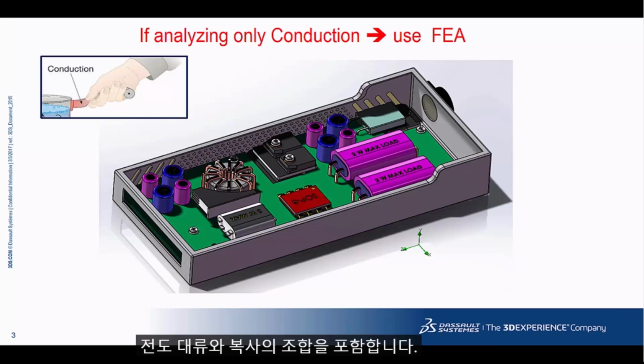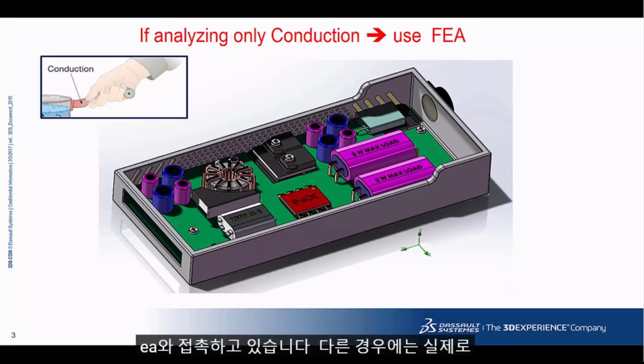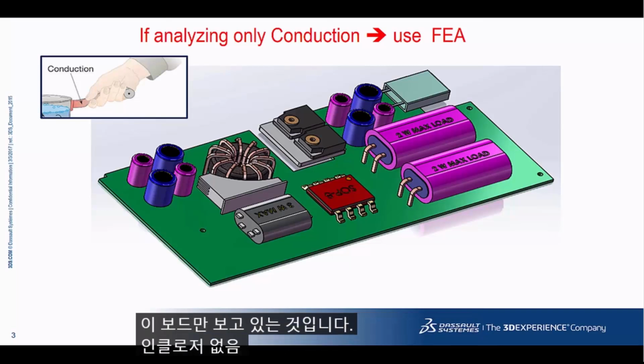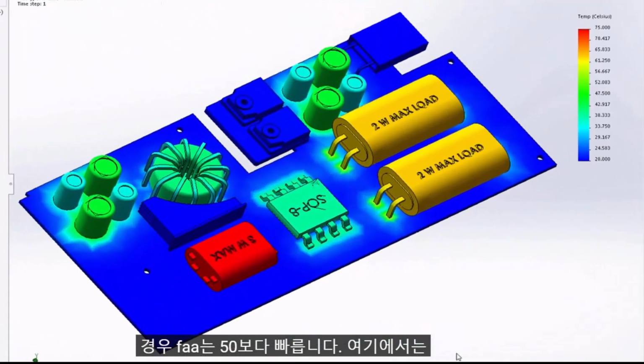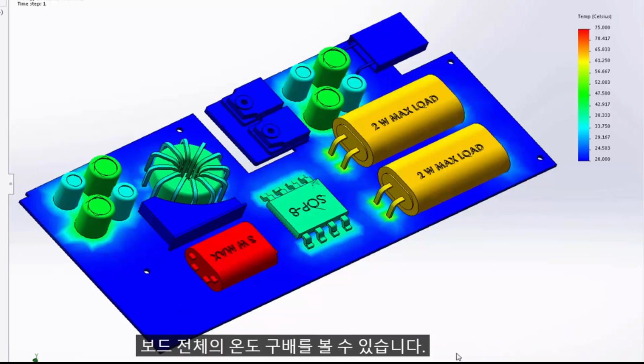Looking at this electronic enclosure, if you are only analyzing conduction between components which are in contact with each other, then you are really looking at this board only. No enclosure, no fluid, no air around the components. In this case, FEA is faster than CFD. Here is the result of the FEA analysis with conduction only. You can see the temperature gradient across the board expressed in colors.